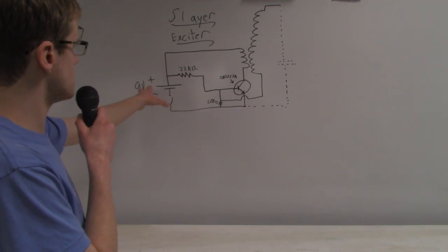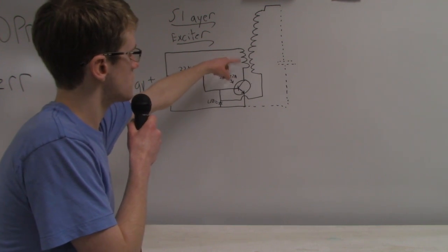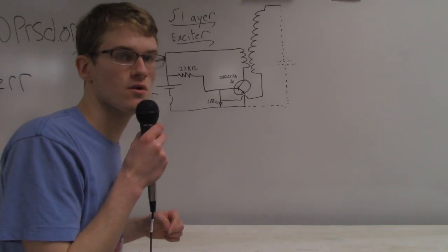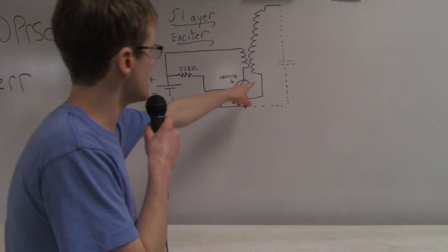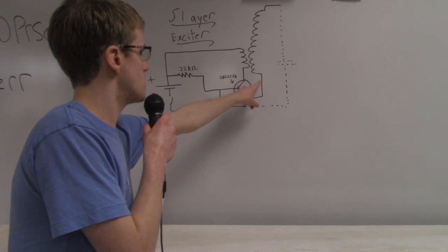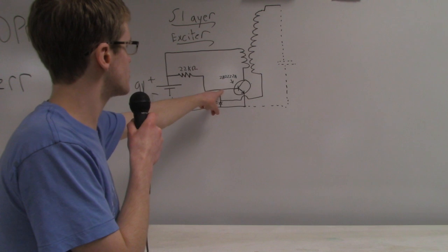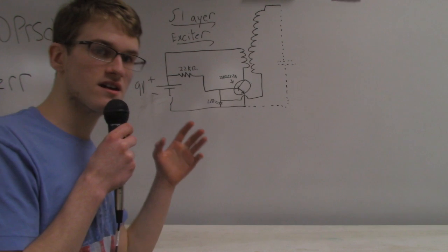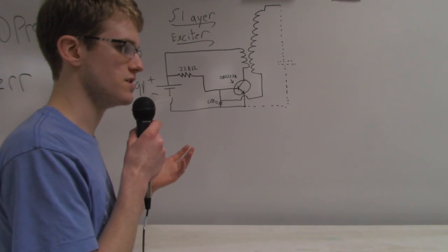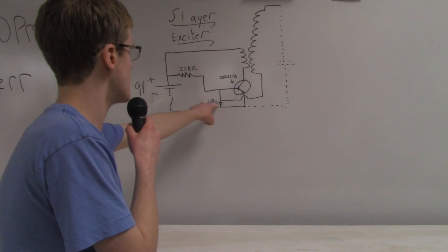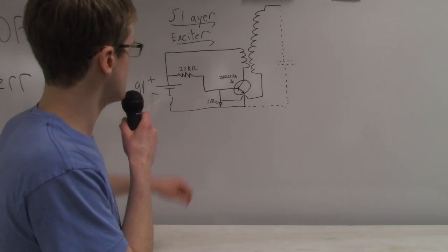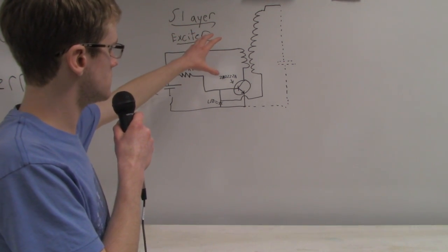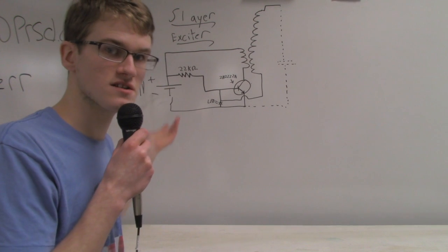Once this occurs, it causes a magnetic field to be generated in the vicinity of the primary coil, which induces a large voltage in the secondary coil that you see. And at the bottom of the coil, that voltage is negative. So that negative voltage is then attached to the base of the transistor via this cable, and it does two things. Since it's negative, it shuts off the transistor because you need a positive voltage. And the other thing it does is it illuminates this LED referenced to this part of the circuit. And once that happens, you end up with a flash of the LED, and the circuit turns itself off. And then, of course, the process starts all over again.